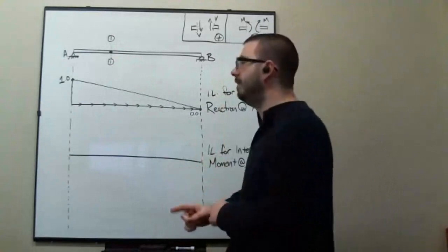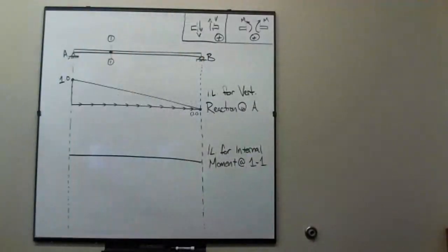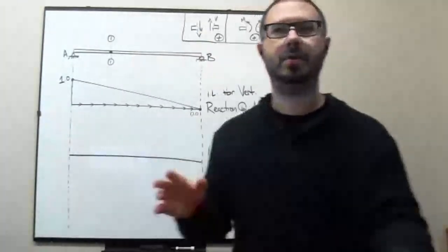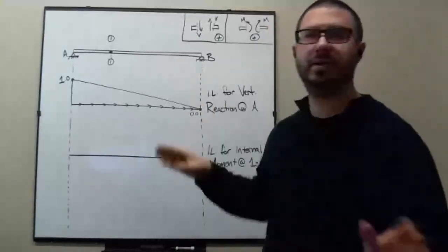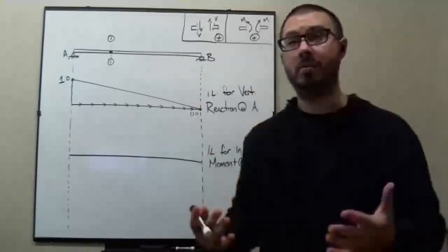Now here's the tricky part. I need to take that structure and I need to move it through a unit displacement, or unit deformation. That's what the Müller-Breslau principle states. I need to move that structure through unit deformation. Okay, so we're talking about moment.